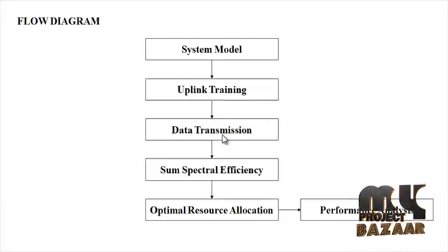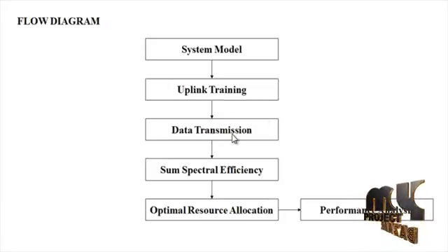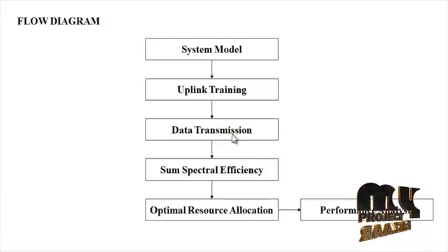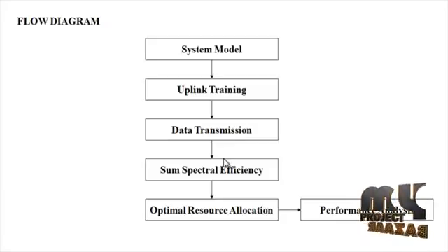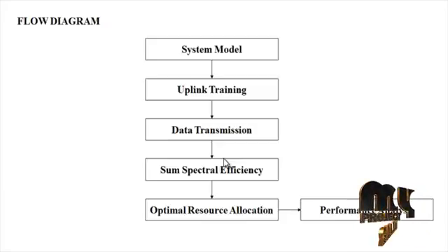Next, in the data transmission, all K terminals send the data to the BS, and x_n is a vector of symbols transmitted from the K terminals in the nth cell. The N cross 1 received vector at the BS is given by. Then BS uses MRC together with the channel estimate to detect the signals transmitted from the K terminals in its own cell.